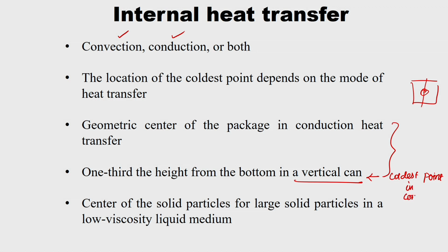In convection, right. And the center of solid particles, for large particles in a low viscosity liquid medium, is nothing but... your viscosity will not add any extra resistance, because viscosity is nothing but a flow resistance, right. So, if you have flow resistance and you are using heating, it will reduce your viscosity a bit, but it will add up to resistance. So, if it is a low viscosity liquid medium which has large solid particles, it is mostly taken as conduction. So, the coldest point will be in the center of the solid particles.